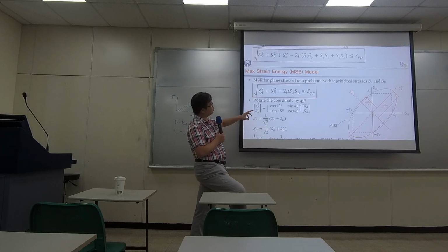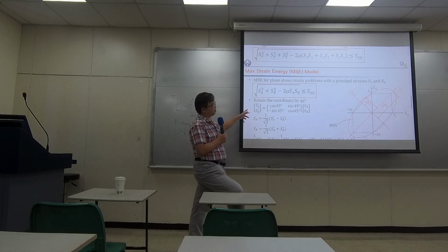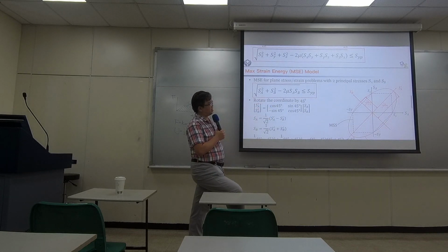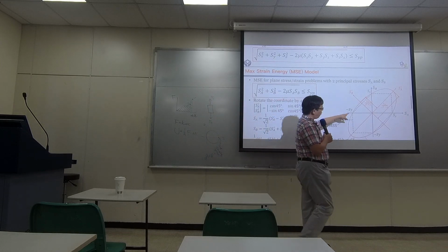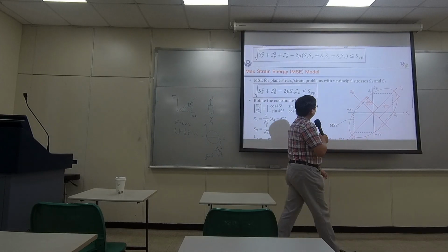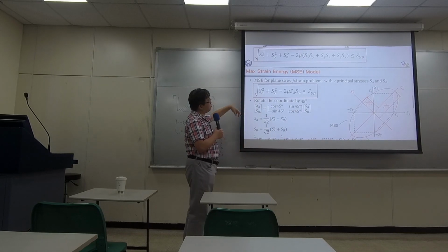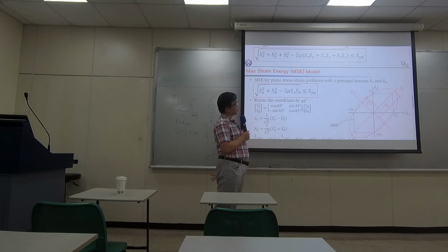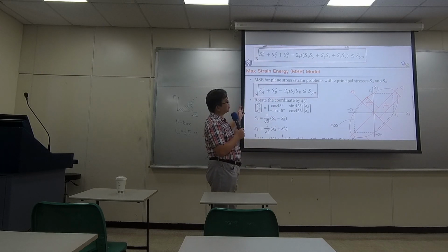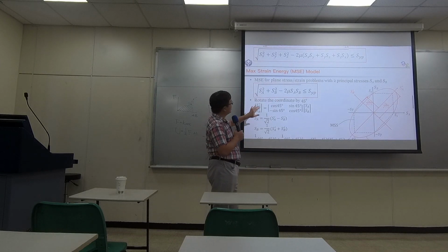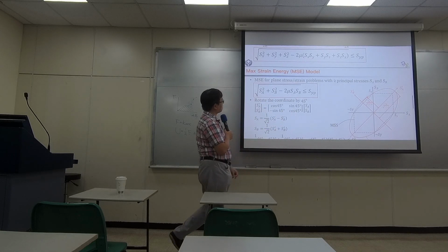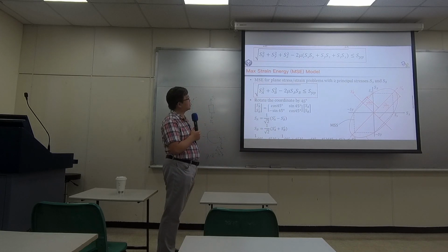It doesn't matter which one is the bigger one, okay? And that's how we derived the 6 equations for maximum shear stress. So we did the same thing this time. I just named the first one SA, and the second one SB. It won't be any different if I swap the definition of SA and SB. Same drawing right there, because it's going to be symmetric.